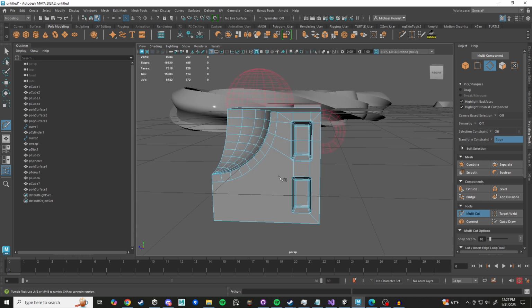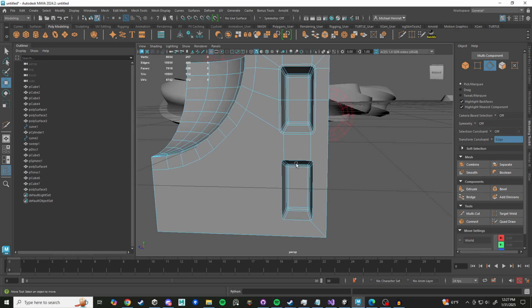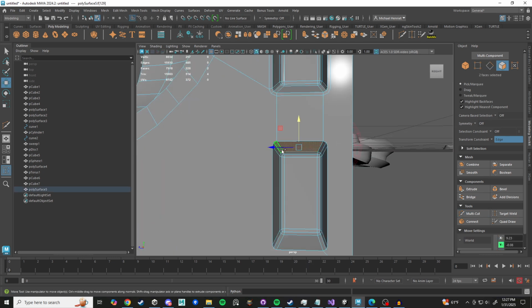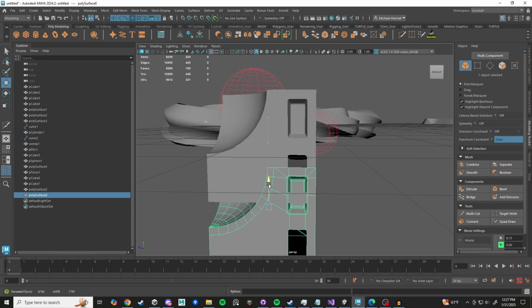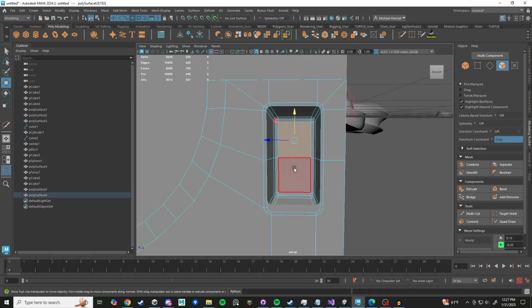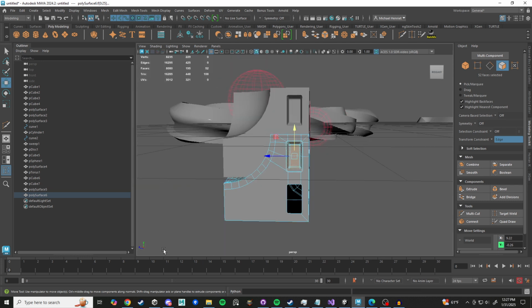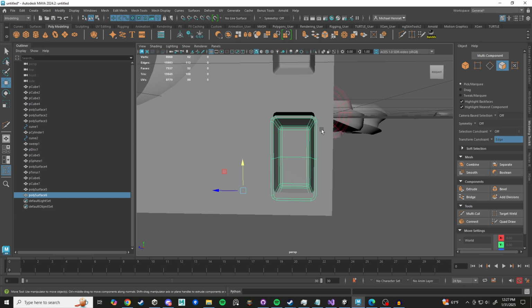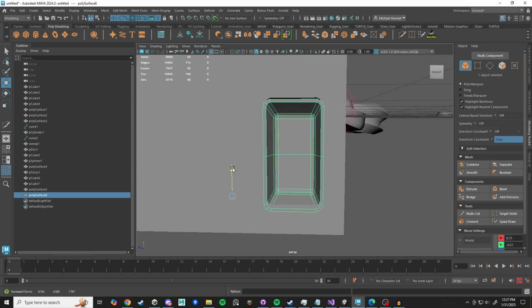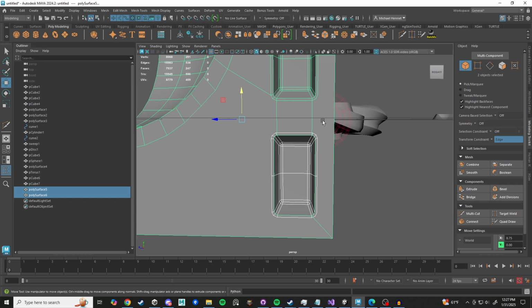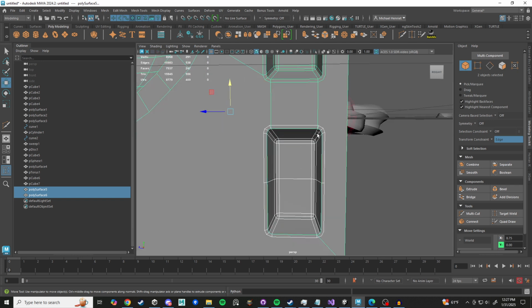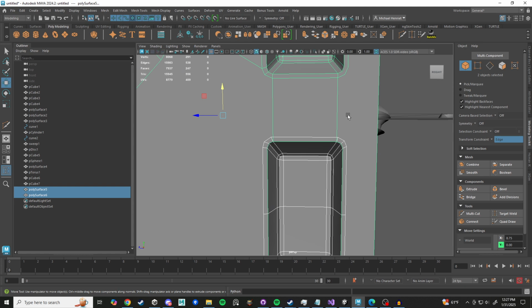And like this, I wouldn't want to make this thing again. Instead, you can take some shortcuts. Like we already made one of these that looks nice. So why not just duplicate that, move it down, and I'm gonna grow my selection with shift period. Shrink is shift comma, and then I'm gonna invert that selection, delete that. And then we can just align some of these points in here like this, and then I'm gonna align it right there. And then we don't have to worry about some of those points that we were moving around before.